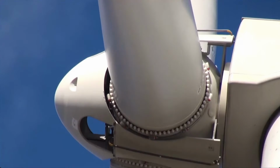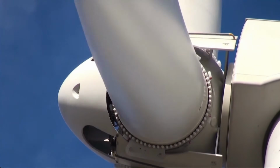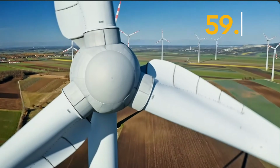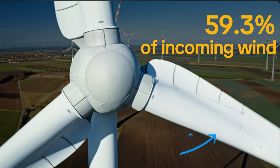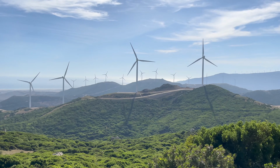So, to really understand the root cause of this issue with blade design, we must talk a little about the Betz limit. You see, in practice, a wind turbine, regardless of its number of blades, cannot capture more than 59.3% of the energy from the incoming wind. This percentage is the maximum efficiency possible of any wind turbine, regardless of its shape and size.